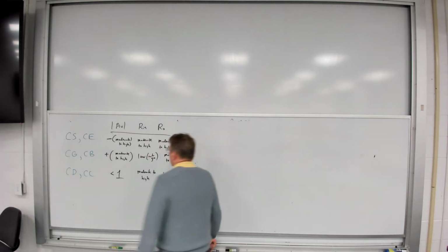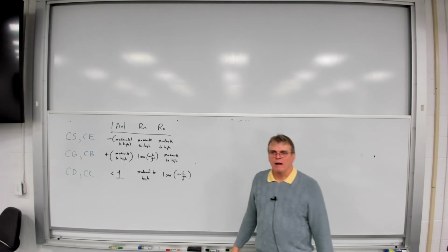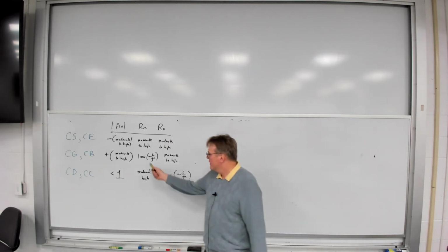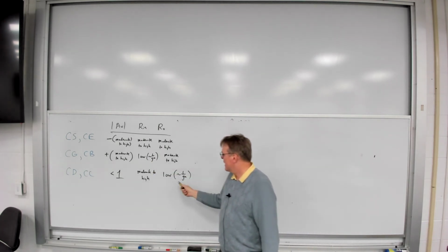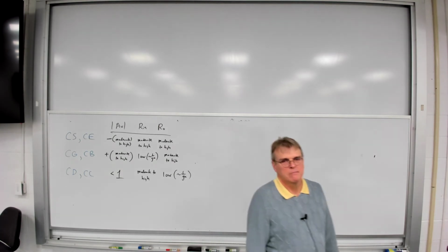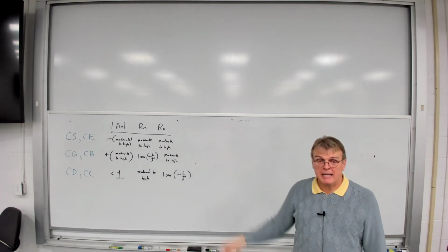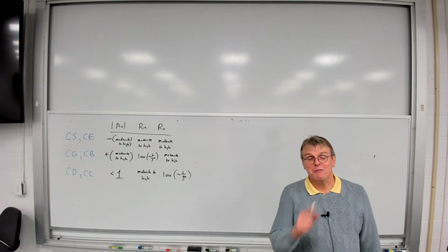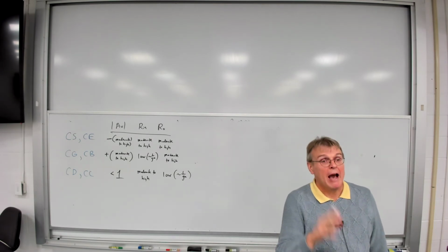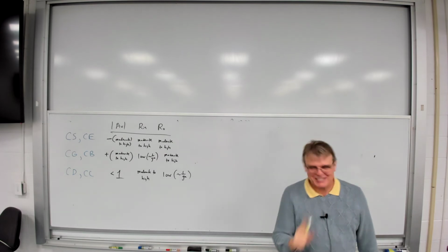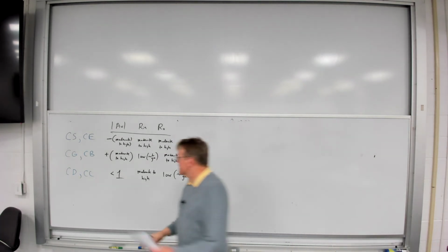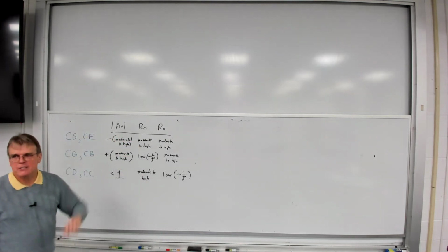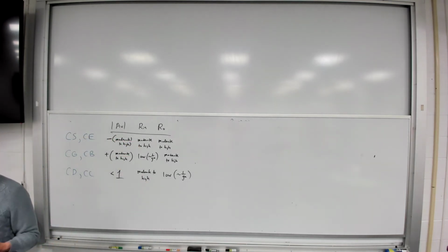Now incidentally, what if I needed an amplifier that had both low input resistance and low output resistance? Does this mean I can't possibly build an amplifier like that? Well, put it in a simpler way, I'll need more than one transistor, right? Exactly. And we'll talk about that later. Obviously, if I need something with properties outside of this table, I need more than one amplifier. I need to combine transistors together, build a multi-stage amplifier, for example.